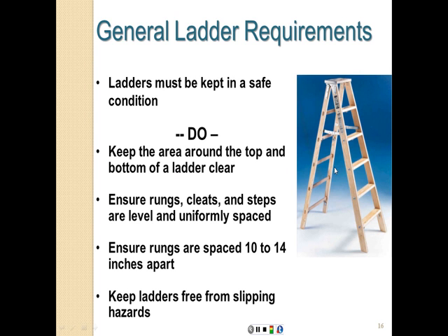Again, similar to what we had in the stairs, for the uniformity you should not have any difference more than 1/4 of an inch. Climbing a ladder is a sort of mechanical motion, so you want your hands and your muscle memory to adjust to that height without much difference in the distances between the different steps. Ensure rungs are spaced 10 to 14 inches apart. Less than that is going to be too cumbersome, and more than that is going to be far harder to reach. Keep ladders free from slipping hazards.